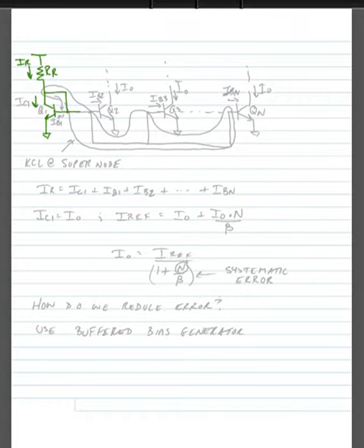And of course the reference current flows partially into the collector, IC1, but we also get some base current that flows, IB1 here, and we're going to connect this reference generator up to a number of other current sources. This current source goes to bias some circuit, the current I0.